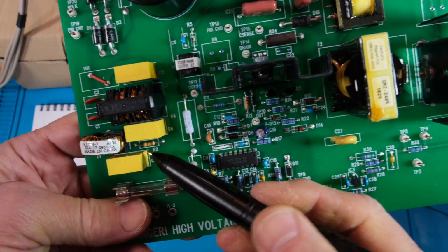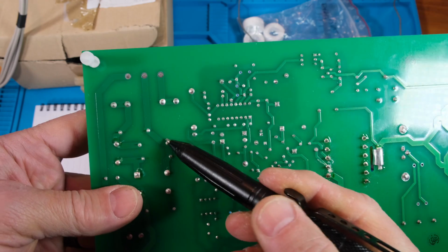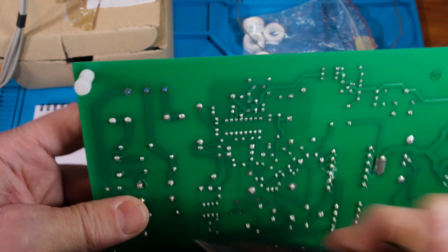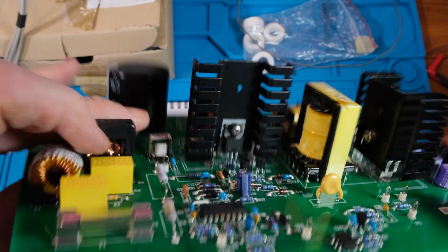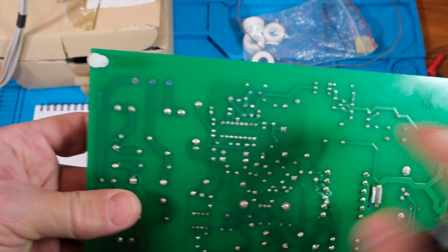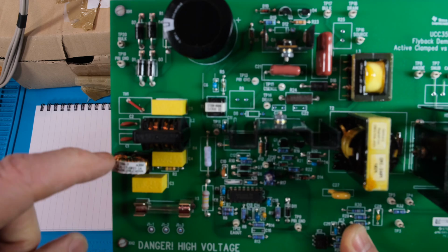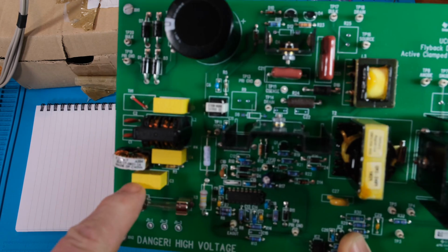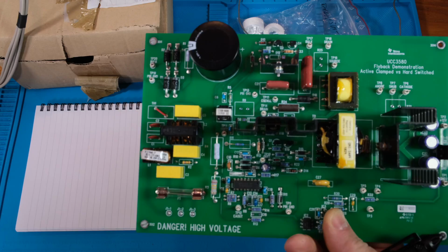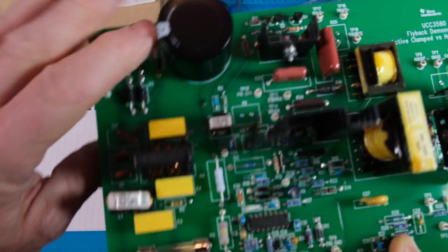But look, there's also a resistor down here. Let's see where that's tied. So it's tied right here to right here. So it's right in parallel with that X2 cap. Okay, it's on this side of the differential mode. Then the differential comes to this X2. So this guy and this guy are in parallel. So let's go ahead and draw that. And then we have our Y caps here. Let's jump over and look at our Y caps.